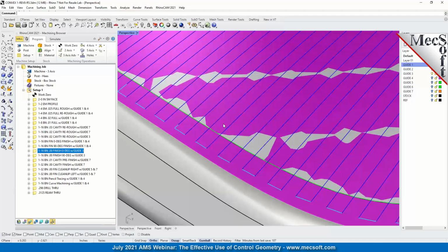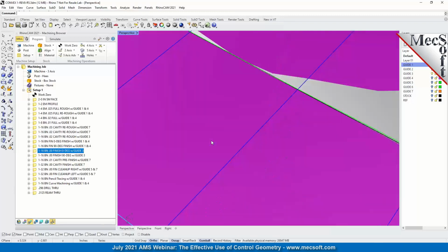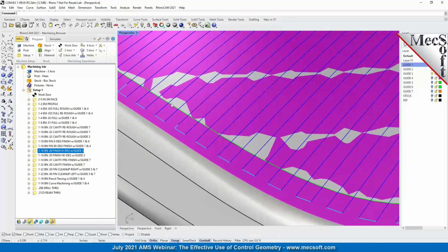So it adheres to the rule of a mold maker. Proudly, I'm an old mold maker, old as in I did it a long time ago for a few years. And as a mold maker, anything you can do to protect your parting line, you do, because when you supply parts for first piece inspection, that's the first thing they're going to look at: your parting line. If you got a nice, tight, clean parting line, that's representative of a quality mold shop. So this is just one tool that you can use to affect that quality and accuracy at your parting line.